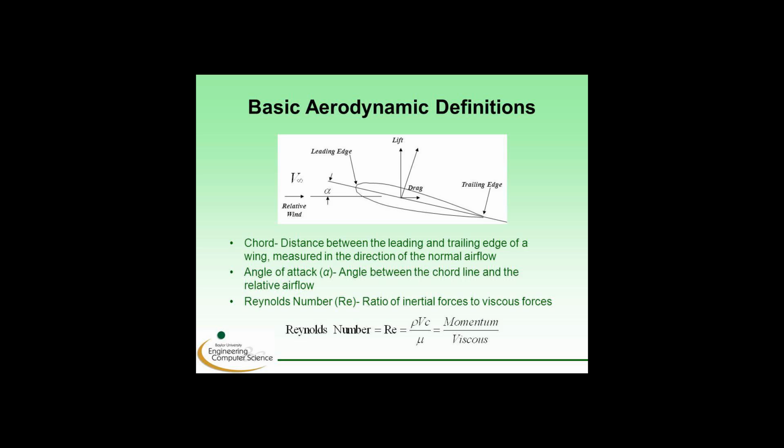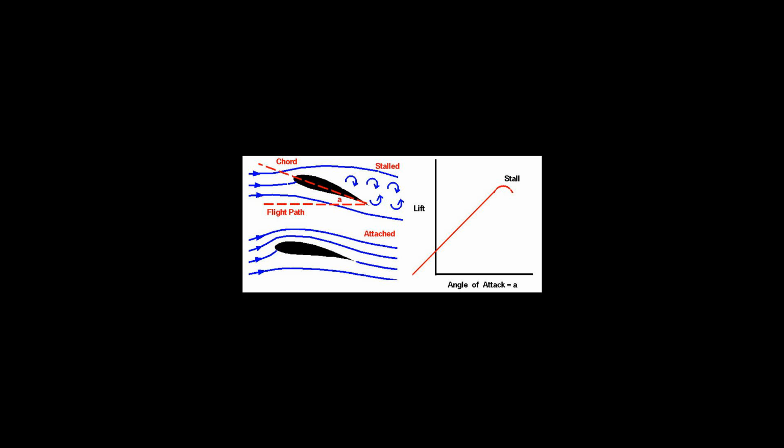The MAC is a two-dimensional representation of the whole wing. The pressure distribution over the entire wing can be reduced to a single lift force and a moment around the aerodynamic center of the MAC. Therefore, not only the length but also the position of MAC is often important.